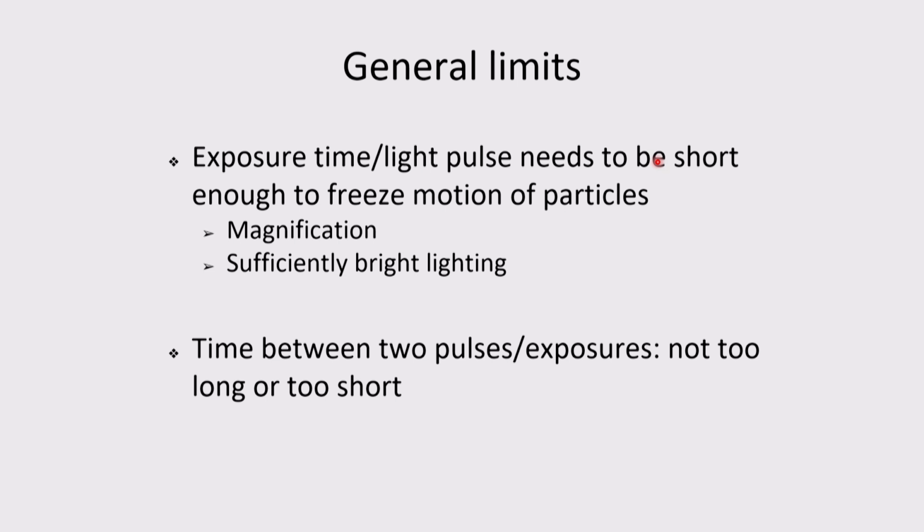The general limitation is again that if the exposure is long, instead of seeing the particles you see a lot of hazy stuff. Maybe we can just demonstrate that also. If you use an SLR camera and the flow is very fast, you just see something like smoke going. If you can't distinguish particle pairs, it will be difficult. And then there is the time between the pulses. Let's say some flow is going.